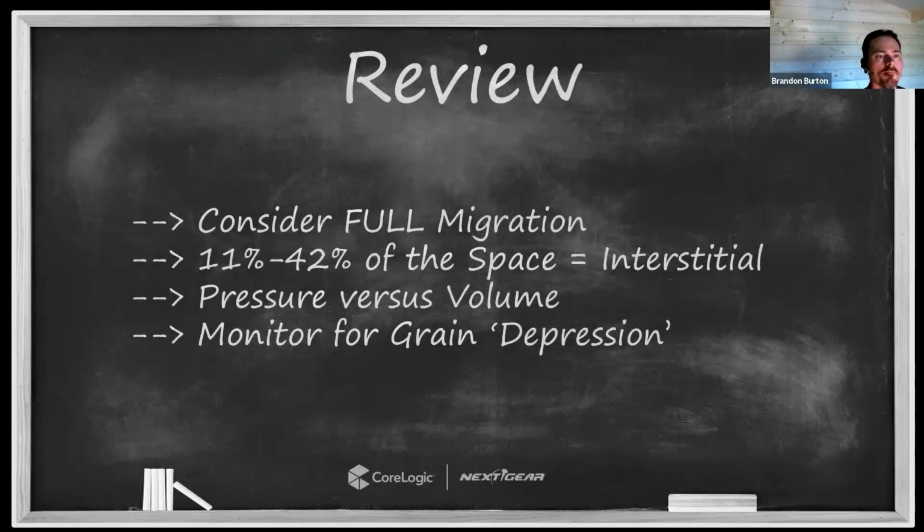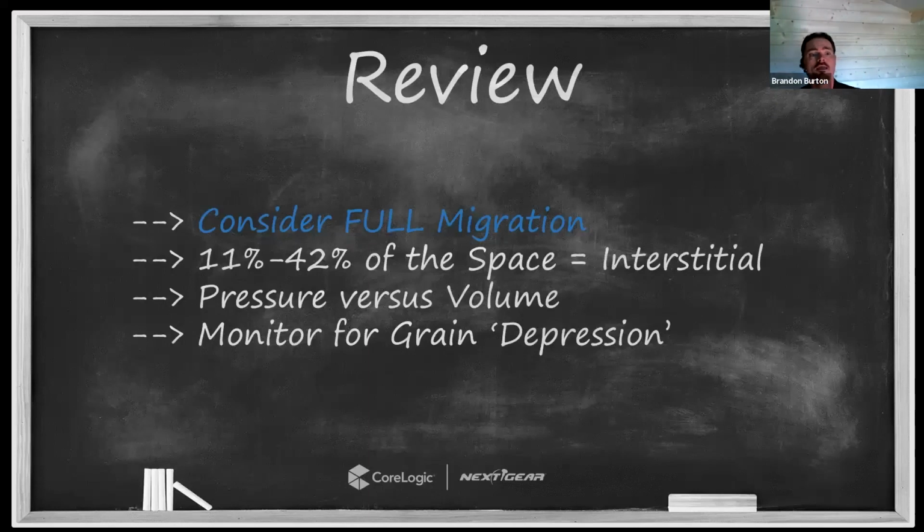Number one in the review, remember to consider full migration when you're looking at a water damaged space, right? It's not just what you can see that we're trying to dry. It's everything that has become wet and affected within that environment that we have to monitor, that we have to dry, we have to validate has achieved its drying goals. That means we need to think about assemblies as their full list of components and all the cavities that they create in between. That means my drying chamber isn't just what I see.